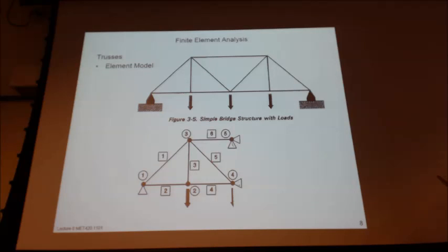And node 5 we had to create for element 6, which is now half as long. But note that element, that big long beam at the top of the truss, is not going to deflect or deform in the y-axis. So we have to constrain that node 5 in the y-axis to behave just like the full truss element would. Okay, does that make sense? Questions about that?